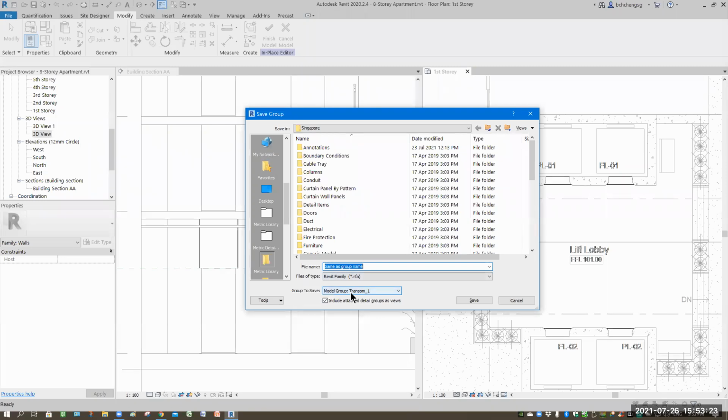So initially, if you don't create it as a block, as you guys know, people will tell you the model in place library you build is not transferable. So you must always think of a way to export out, like what I'm showing you here. Questions? Remember to choose the correct component, because sometimes if you don't highlight it, this will show you all sorts of different listings. So I want to export this out as a family RFA. Then you scroll to see where you can save it.